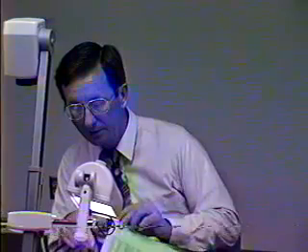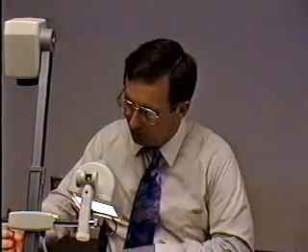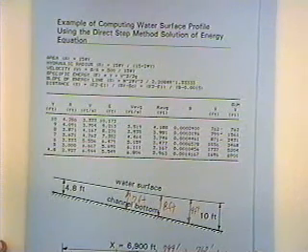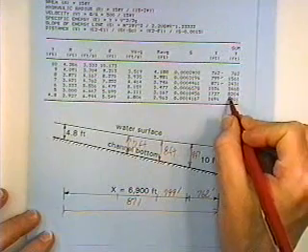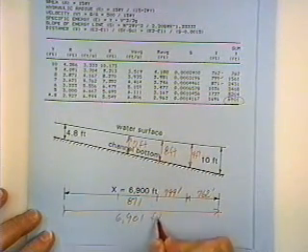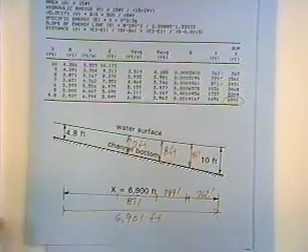And just for fun, I ran this out on a spreadsheet with different step sizes. And by the way, the total distance down here at the bottom, all the way from 10 feet to where uniform flow occurs here, is this number, the 6,901 feet. And that's using the 1 foot step size. And I just did the computations over. You've got a couple other solutions in your notes there.